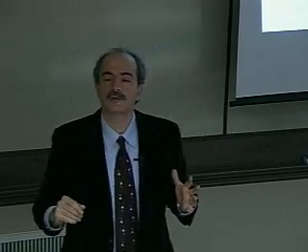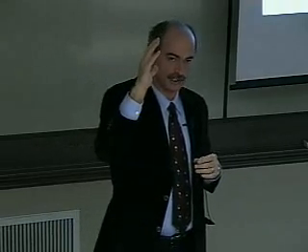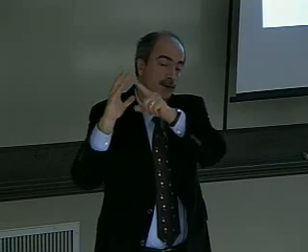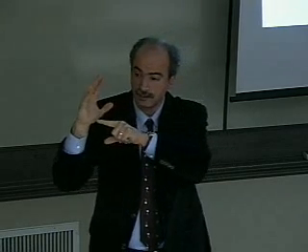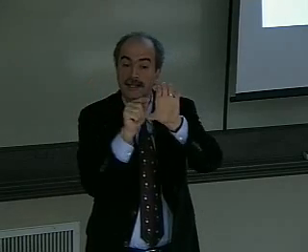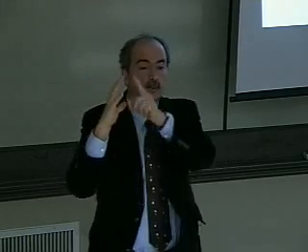We could do this also electronically. Instead of a single element transducer, if we have an array of elements, electronically we change the phase of these different elements for their excitation, and then we could move electronically without ever moving the transducer itself. And that's what I'm showing here.